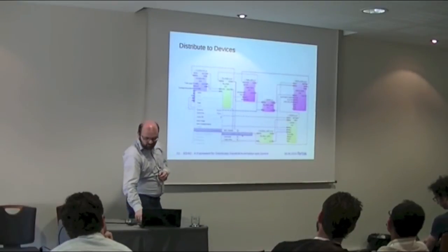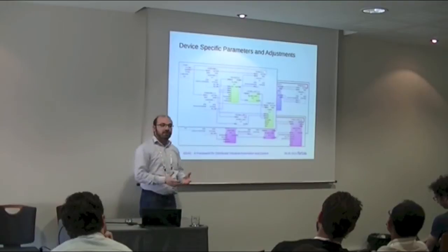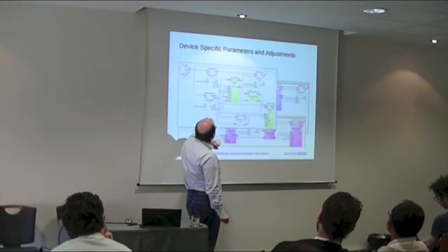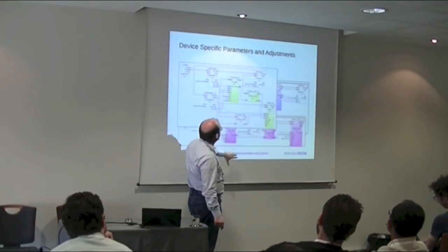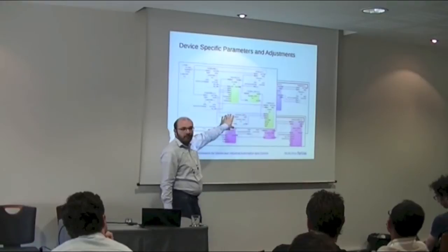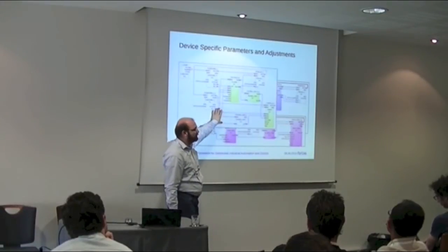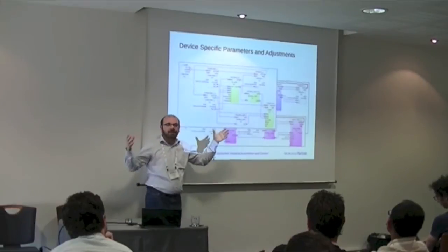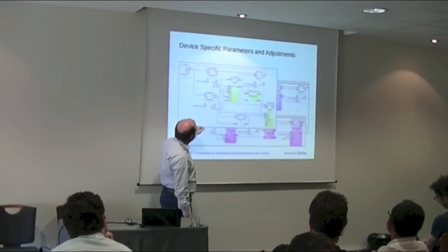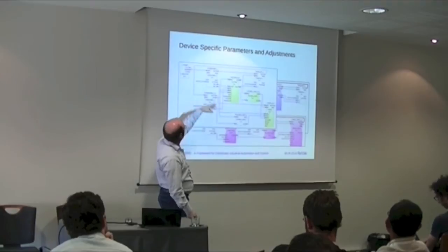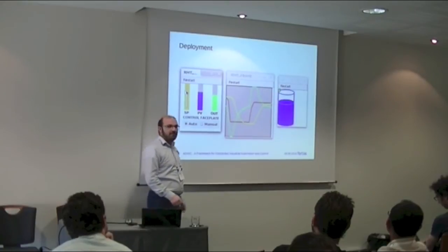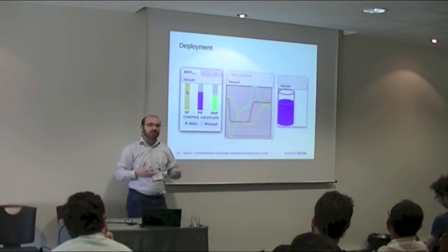The next step we need to do is to add additional function blocks, the white function blocks you see here. So you get different function blocks for receiving and sending the values. For example, here I had to add an additional function block for adjusting values because they were not received in the right range, which was not needed in the central application, because in the central application this is this one. So I cannot use it doubly. And when I run this, I can only run it in simulation, but then I get three separated devices which will then interact via communication.